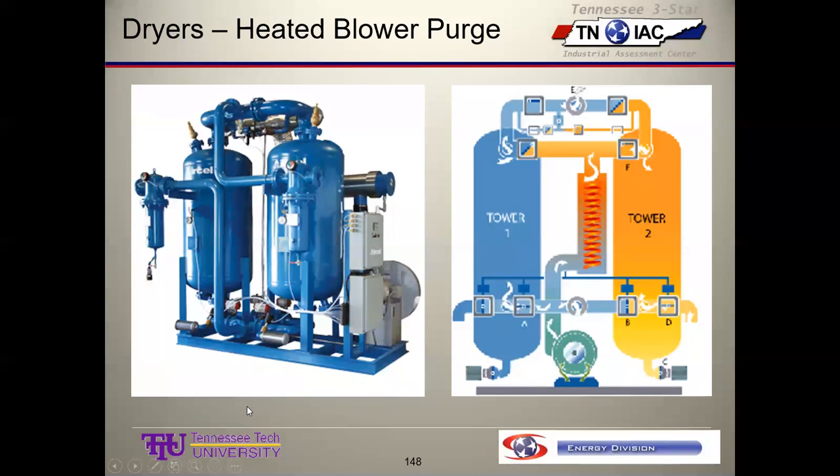If they have desiccant dryers, one of the questions you want to ask is, well, how do you determine when to regenerate your cylinders? Do you do it on dew point switching or do you do it on time? And if they're doing it on time, then that's an opportunity to do a little project and save them some money.